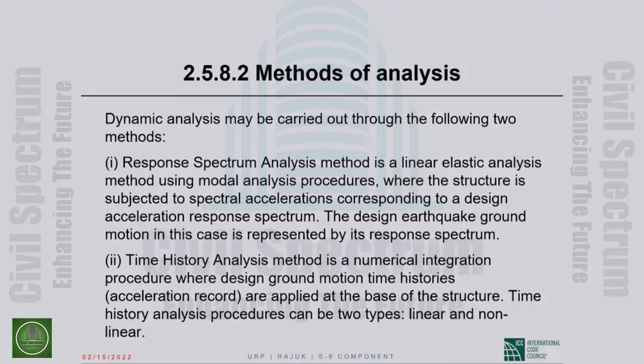structure from structural dynamics. In this type of analysis, if we assume that the structure remains elastic as it undergoes the earthquake ground motion, then we have elastic time history analysis, which, if you ask me, does not give us any more information than modal response spectrum analysis. So elastic time history analysis is something I personally have never been big on.